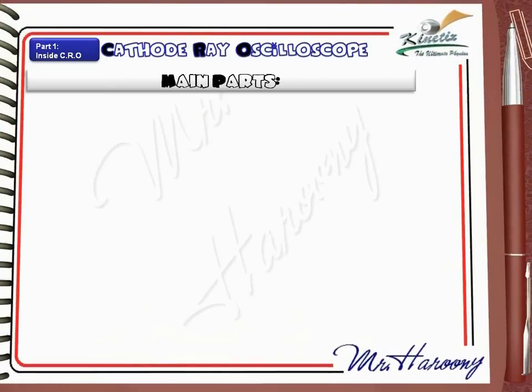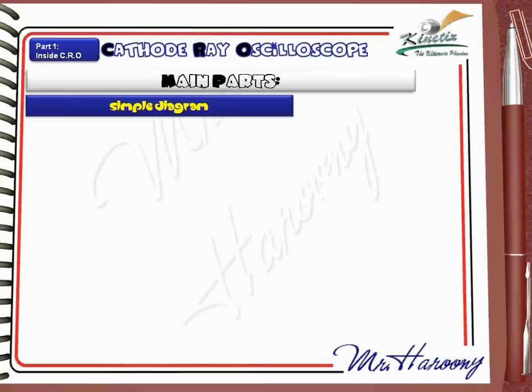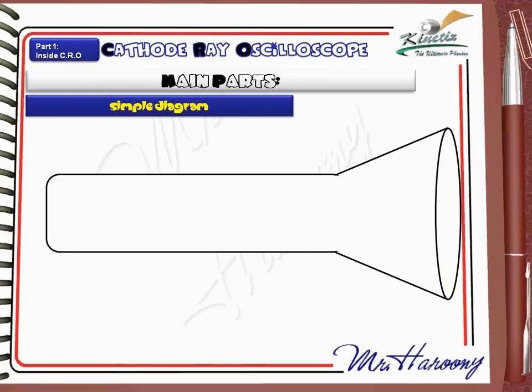In this part, we will learn how to draw a labeled diagram of the CRO. First, you must draw this shape that will indicate the vacuum tube that encloses most of the parts. Starting from the left, the cathode is drawn as a basic cylindrical shape. The heater or the filament with its supply are drawn as a circuit behind the cathode. The hollow tubes are drawn to represent the anodes. Between the cathode and the anode there is a ring. This ring is known as the grid.